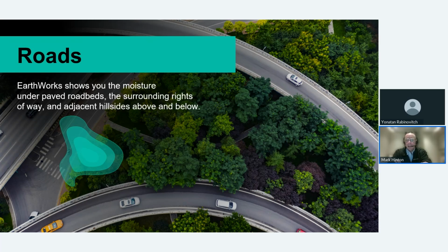So you're picking up potential issues, say cuttings or embankments that are susceptible to failures, or perhaps drainage, which is often a challenge. And when that drainage fails, if you can pick that up early enough, then drainage failures won't lead to further complications and more expense to solve afterwards. So we're picking up issues here that very often wouldn't be visible to visual inspection. There might be surface vegetation, for example, that we would be able to indicate would be interesting to clear out of the way and have a follow-up inspection in certain areas, and you wouldn't know where to do that without this type of tool. So moving on.